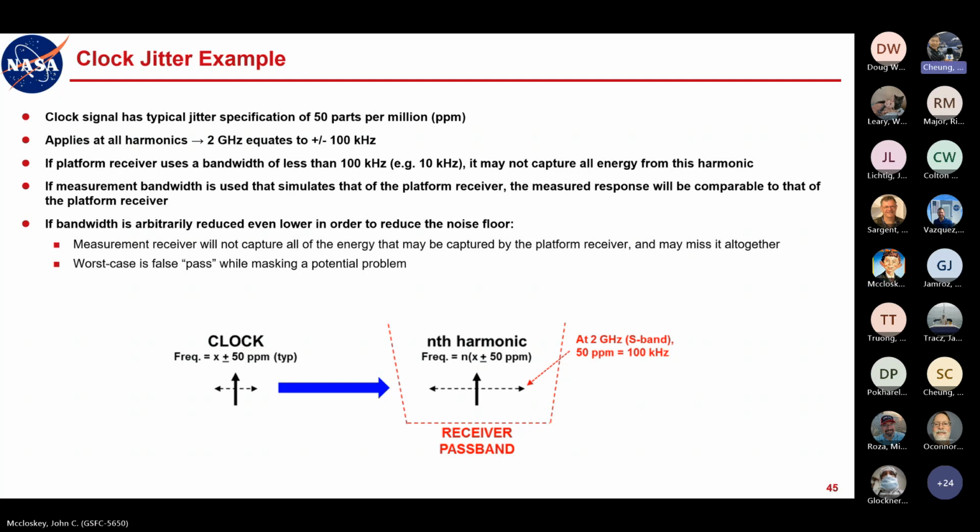Just to be clear, when I say receiver, I'm talking about the EMI receiver, not the flight hardware. Oh, okay. So what I'm saying is, if you are attempting to make this measurement, and the EMI receiver allows you to set a bandwidth that's very, very narrow that cannot be backed up by its clock, isn't that an issue itself in how the EMI receiver operates?